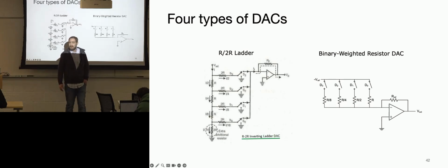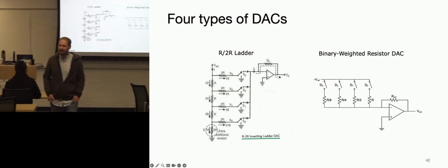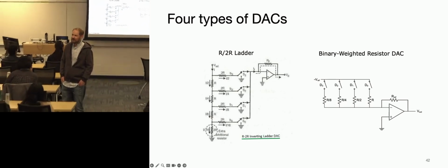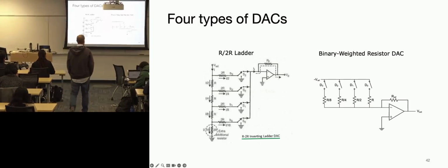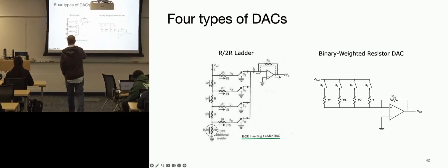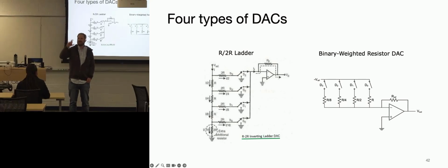I was wondering if you're given a plot of a DAC output, like on an oscilloscope or something. Ooh. You have to use some deduction and some reasoning through that one. You could look through and say, well, here's all the steps I can count. So then you could say, I know it's at least this resolution.